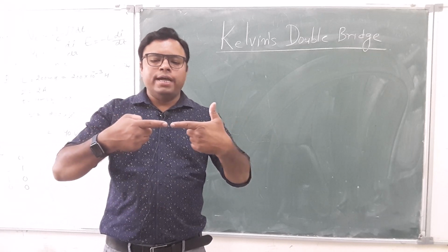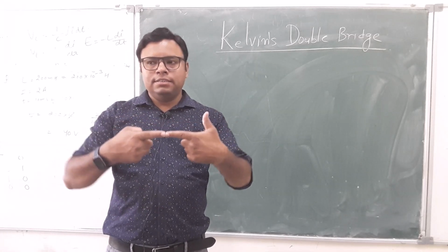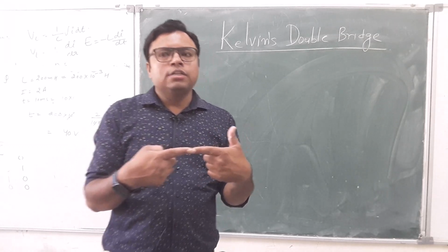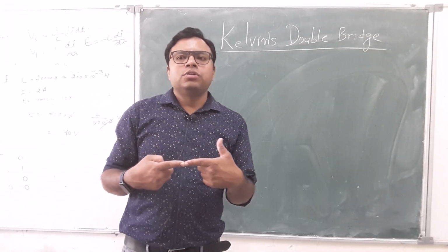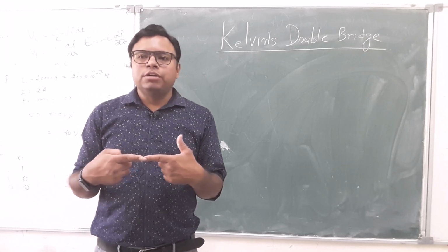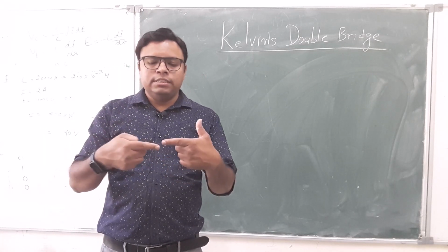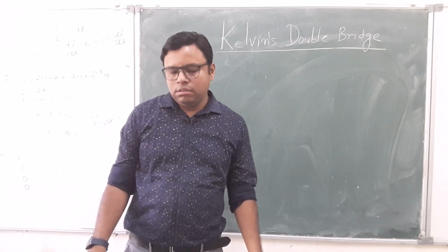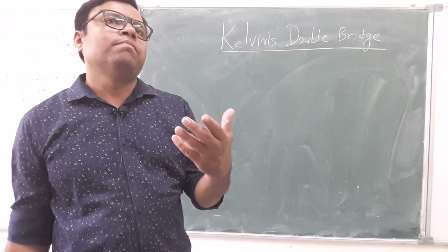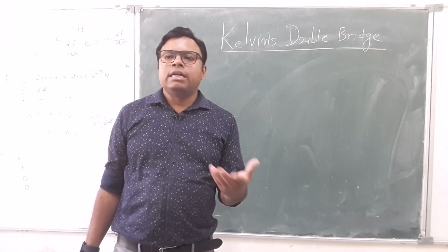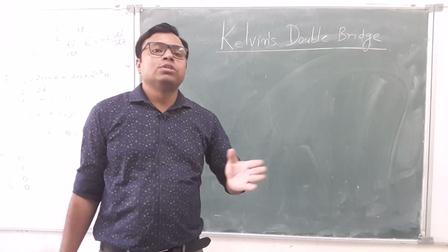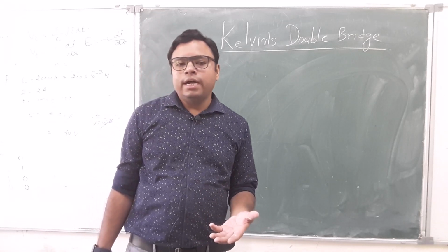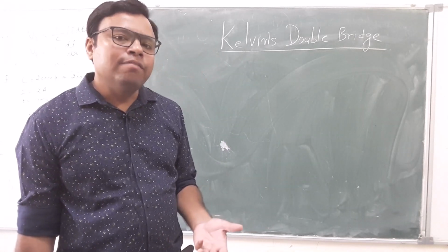When you connect two wires, at the contact there is some different resistance. It also offers resistance that is more complex physics. So that comes in the calculation if the unknown resistance has a value comparable to this contact resistance or lead resistance. In that case, the Wheatstone bridge will show some errors. So to remove those errors, we further develop the Wheatstone bridge and study it as the Kelvin bridge.